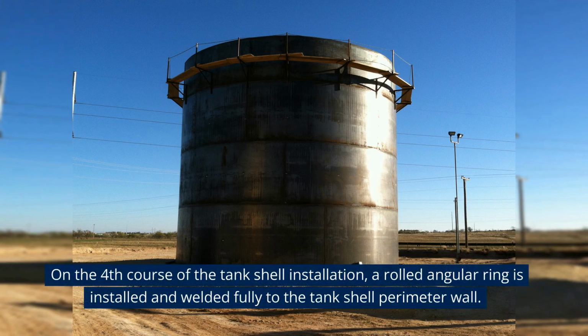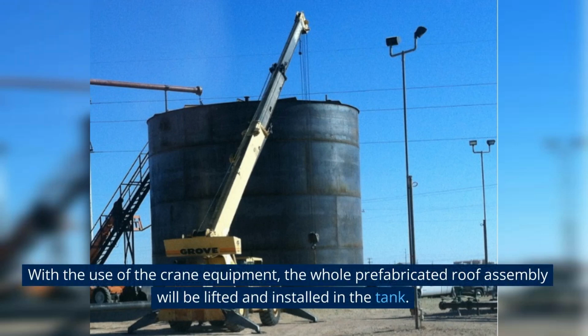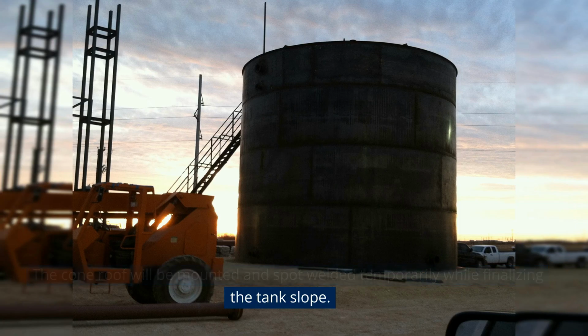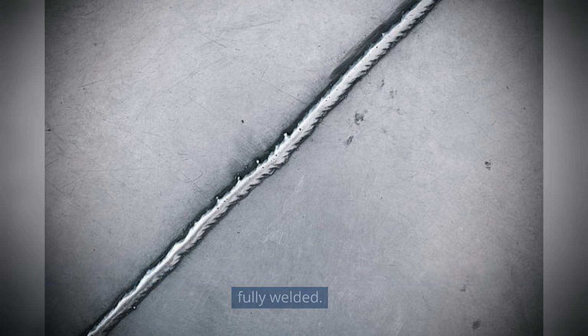On the fourth course of the tank shell installation, a rolled angular ring is installed and welded fully to the tank shell perimeter wall. With the use of crane equipment, the whole prefabricated roof assembly will be lifted and installed in the tank. The cone roof will be mounted and spot welded temporarily while finalizing the tank slope. After the target slope has been set, the last seam in the cone roof will be fully welded.